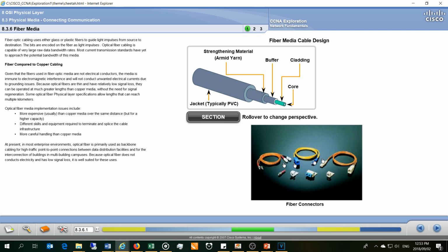You will find these maybe in cars or in high-end home theater systems, for very good noise immune audio transmissions, or especially in the car environment, because there's a lot of electromagnetic noise. We might use fiber optics, or in industrial applications and factories. There we might use plastic cores on very short runs, 2 or 3 or 4 or 5, 10 meters. But in most cases we use glass.